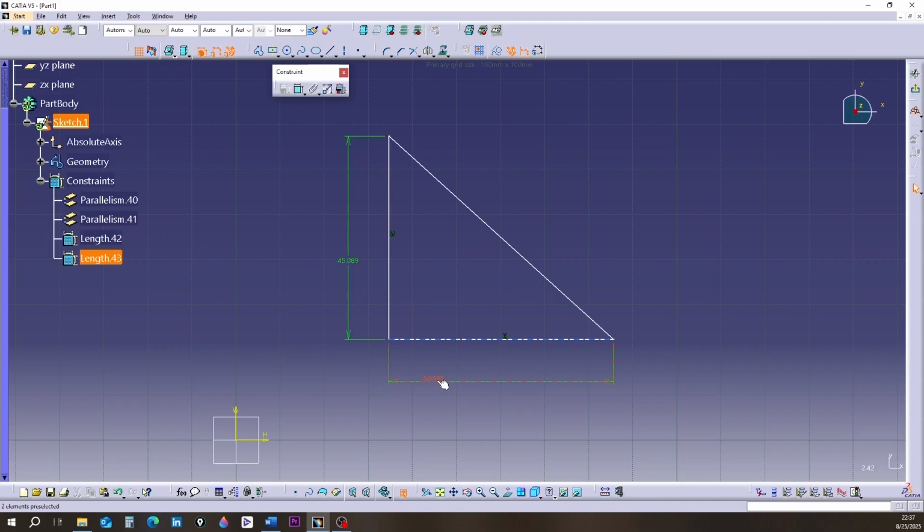By having the dimensions of the two sides of the right angle, the hypotenuse dimension is known. We dimension the hypotenuse. It is observed that the color of the triangle turned purple. The software tells us that over-dimensioning has occurred.